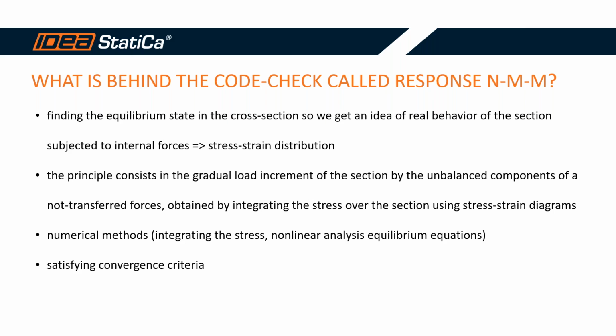The result is a stress-strain distribution with respect to the acting internal forces. The principle consists in gradual load increment of the section by the unbalanced components of non-transferred forces, which are obtained by integrating the stress over the section using the stress-strain diagrams of the particular material.